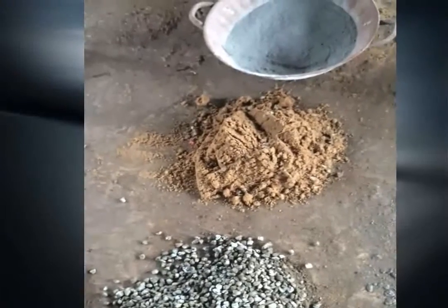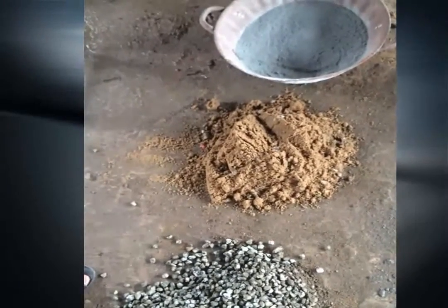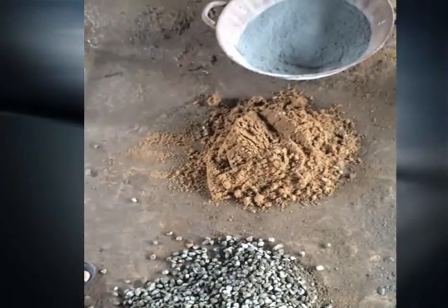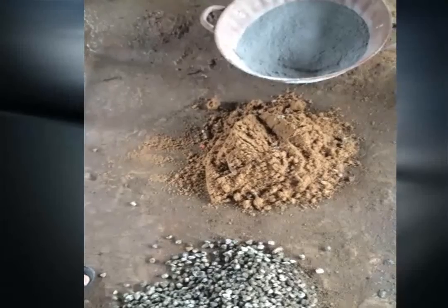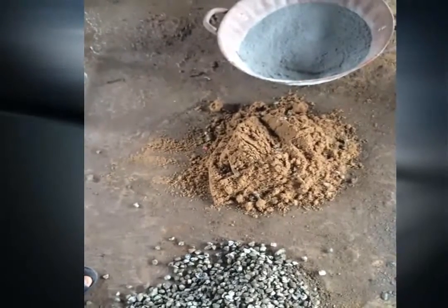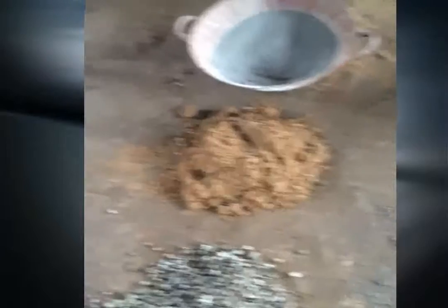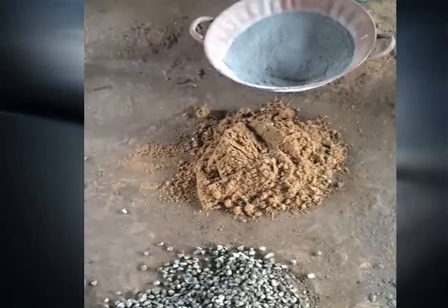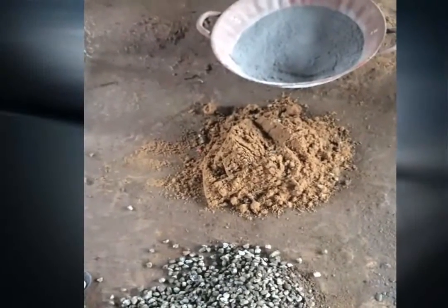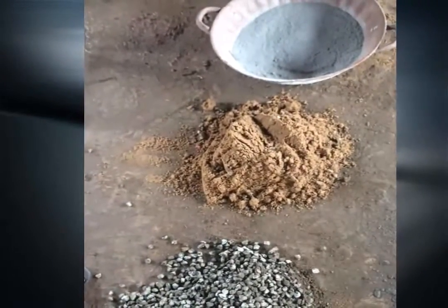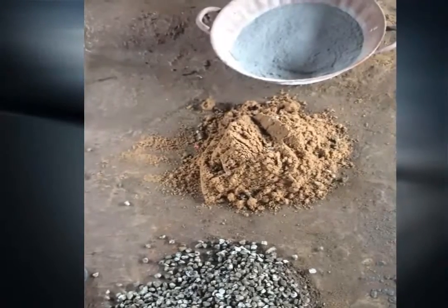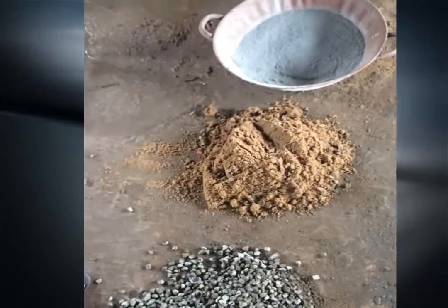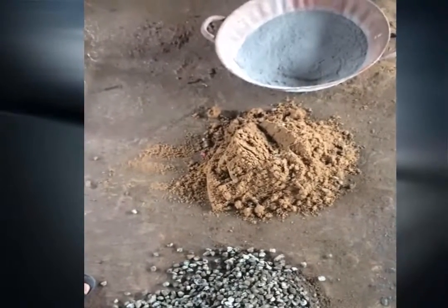About 9 cubes are produced, cured for the respective days, and are taken to the laboratory for testing through a crushing or compression testing machine. The crushing is done at 7 days, 14 days, and 28 days respectively. The cubes are tested for failure, and the load which forces the cube into failure is recorded for 7 days, 14 days, and 28 days respectively.